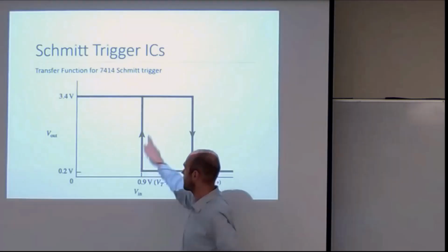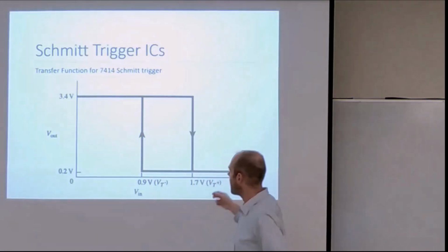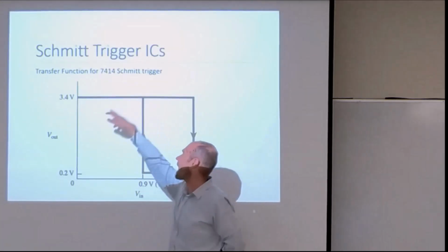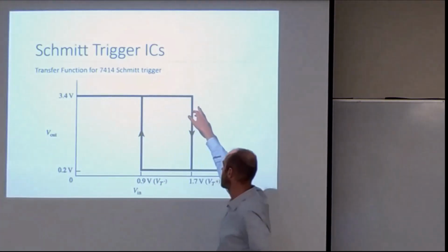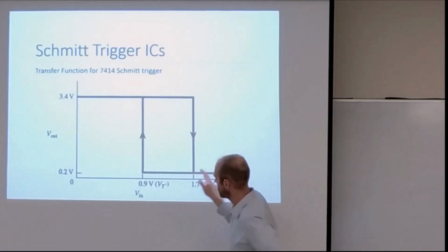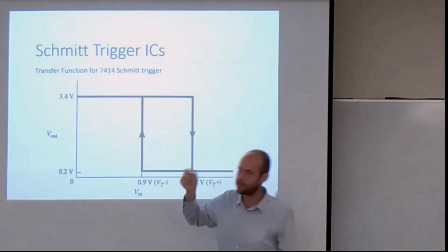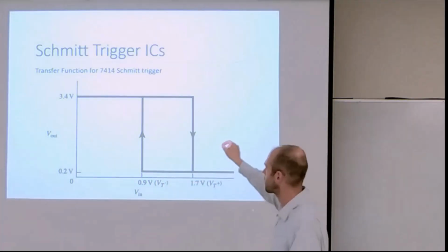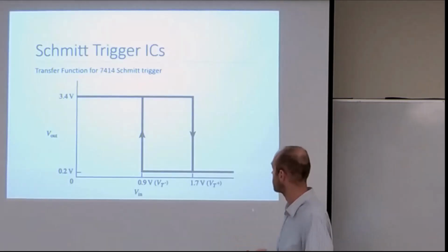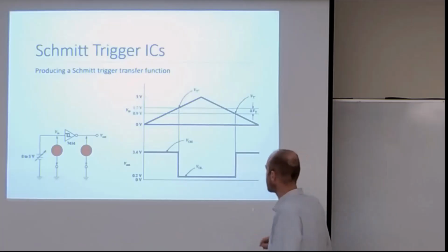But for the Schmitt trigger, at a certain low point we have our high-going threshold, and then you need a little bit higher to get your low-going output threshold. By separating those two, there's a tolerance for noise, so we don't get rapid jittering. So Schmitt triggers clean up noisy signals a bit and speed up transfer.